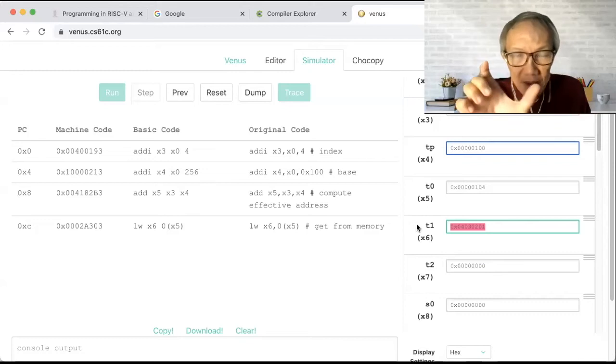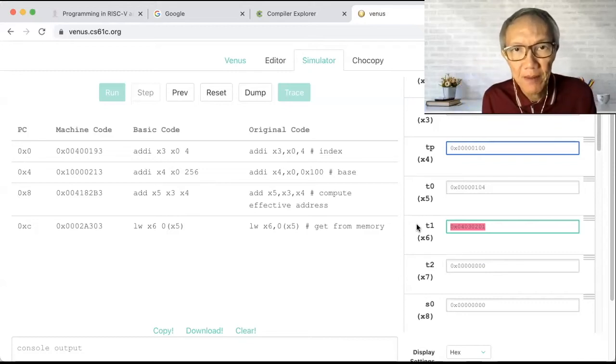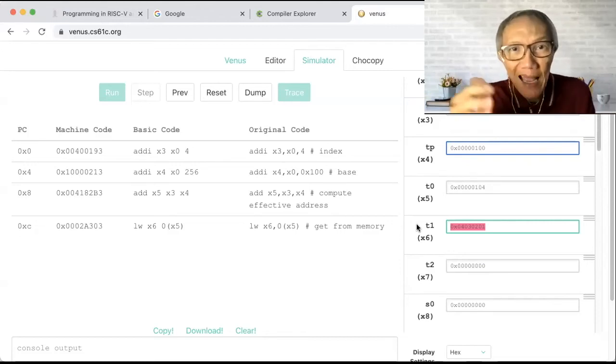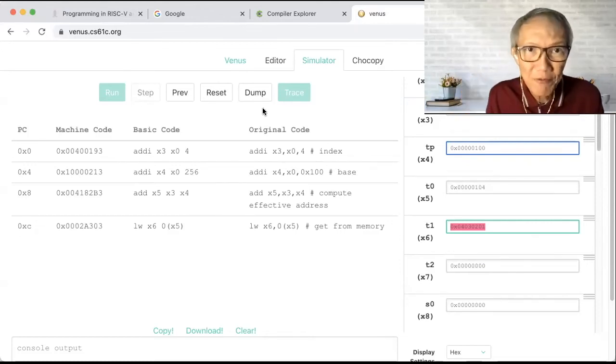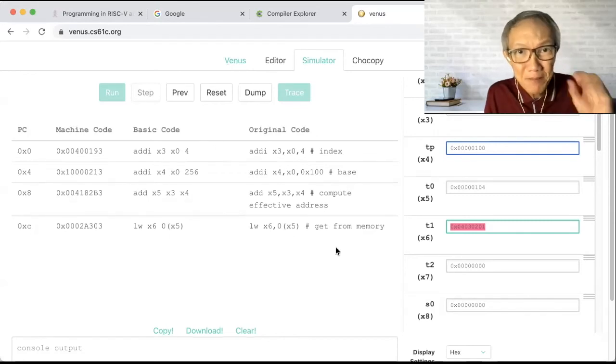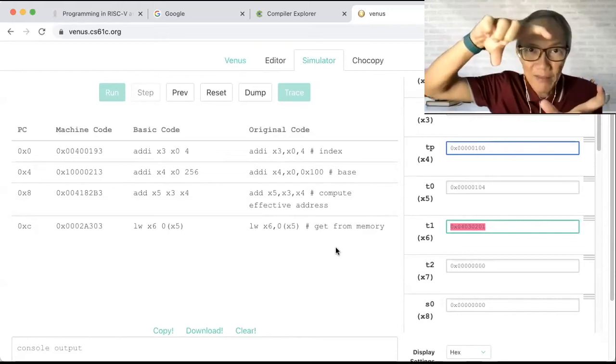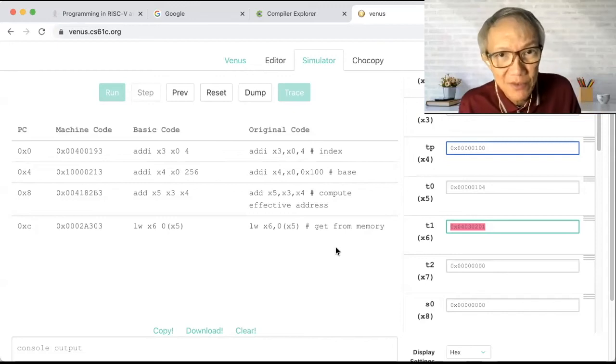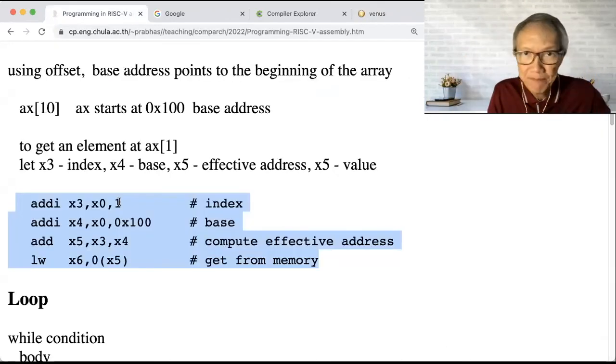Okay, so in the variety of machines in the past, there are 2 camps. One is so-called little endian, and there is another camp called big endian. You have to determine the order of multiple bytes, how when you keep them in the memory, it corresponds to the value in the register.